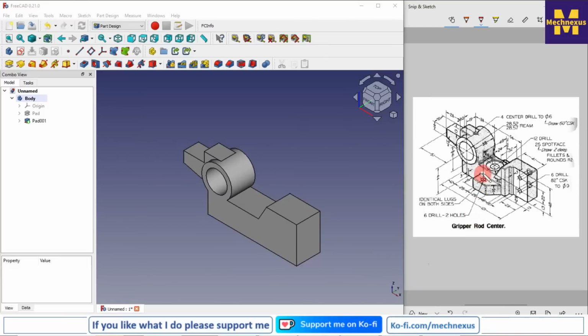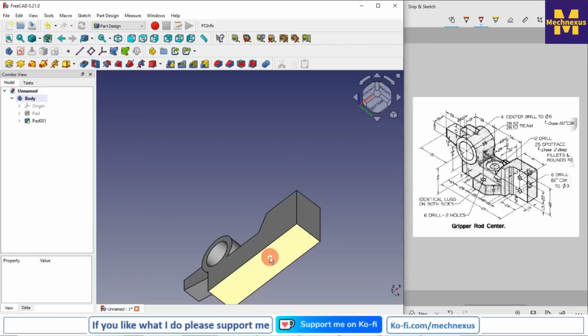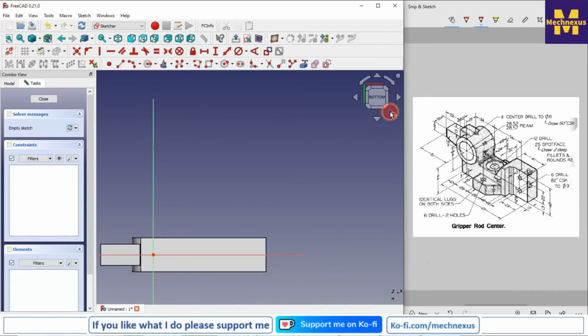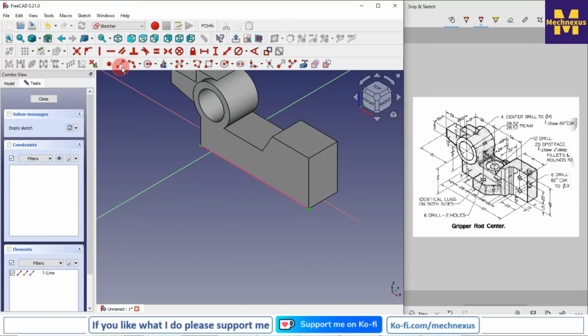Our next feature will be this pad. We will select this bottom face and create our sketch, and from here I will switch to the isometric. So now first we will project this edge. So we will click on the project external geometry and select this edge, and I will select the polyline tool and create a rough profile.